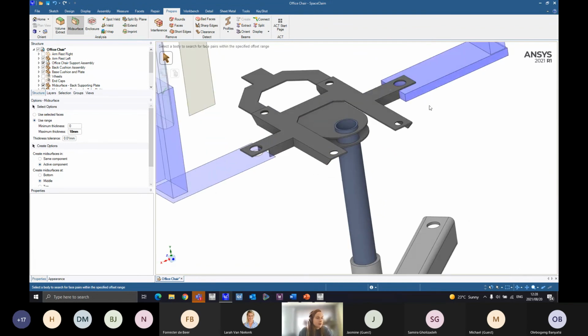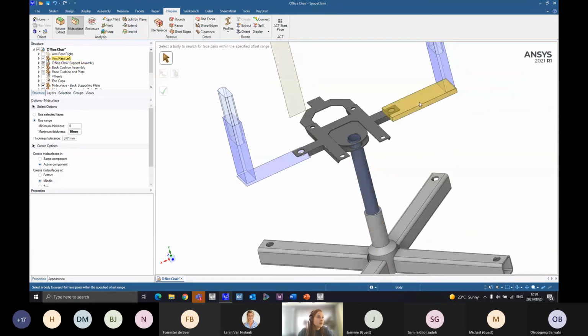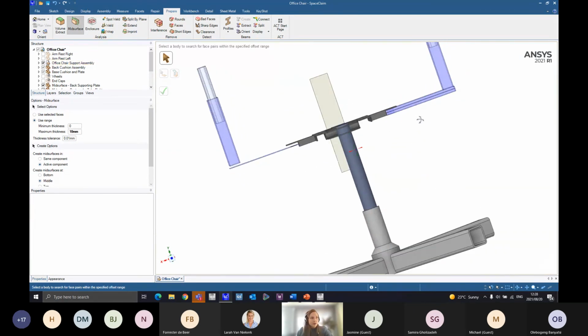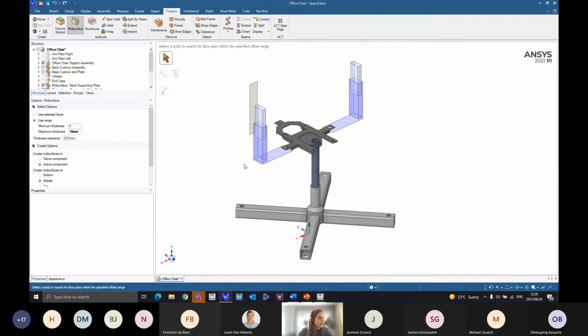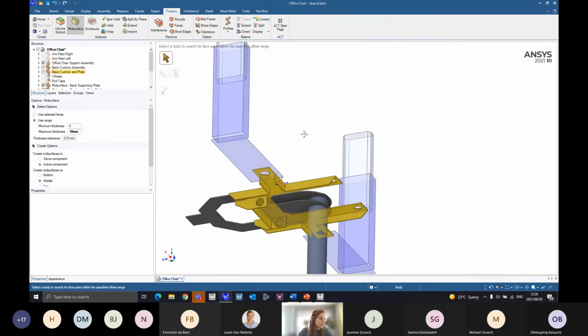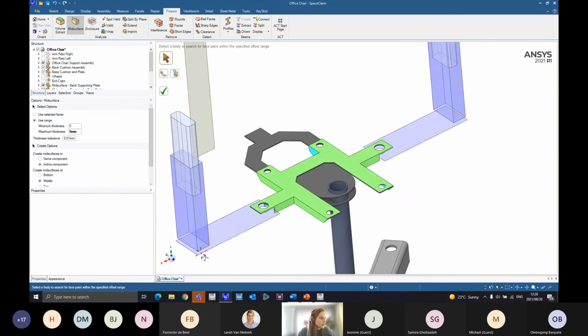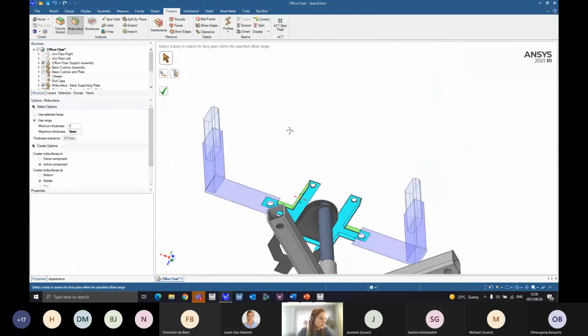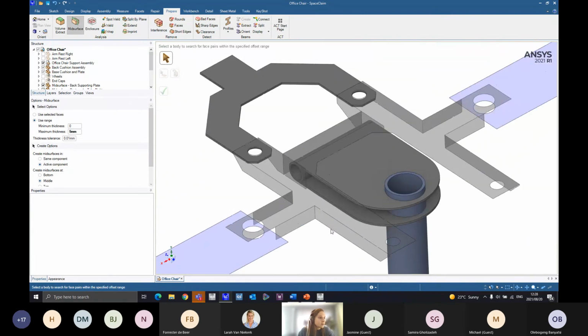So even if it's quite a thick plate or beam or anything, it's still fine to represent it as a shell body. Okay, so those are all fine. I'm going to start mid-surfacing these plates as well. Let's see how they do. I'm just going to change that to 5. Okay, so it's identifying all the faces properly. Let's see. Okay, cool. That seems fine.